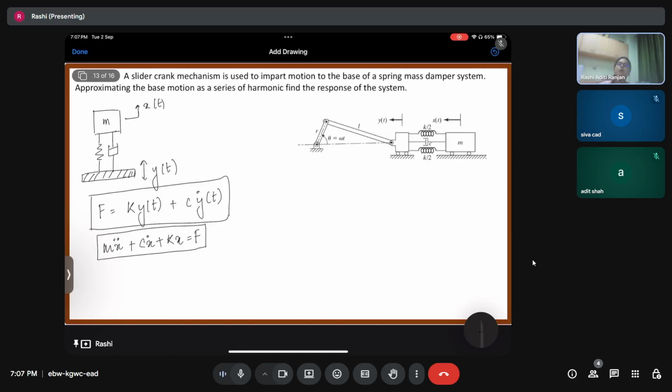So basically, we were converting that into a sum of harmonics because we know the solution that the system is going to have if there is harmonic forcing. So if I convert my periodic forcing into harmonics, it will make it easier for me to find a solution, right? Because even for an ordinary differential equation, we cannot find the exact solution for any arbitrary kind of forcing.